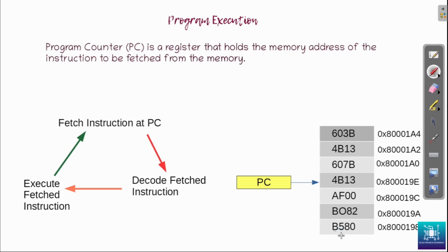So if you have an assembly, the assembly code is a human understandable form, but the opcode is the machine form. So say if you have PUSH {R7, LR}, which I'm picking out from actual code. The opcode for that is B580. That is the operation code. So PUSH {R7, LR} does not go into the machine. What gets written into the flash is this, in the lower memory. So 80 is written because it's little endian. 80 is written first and then B5 is written.